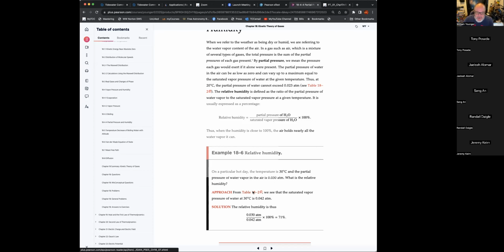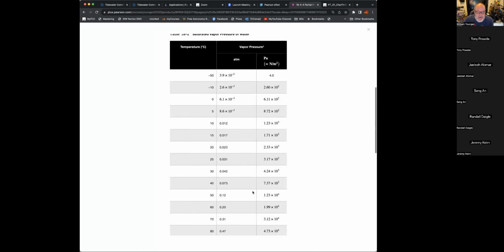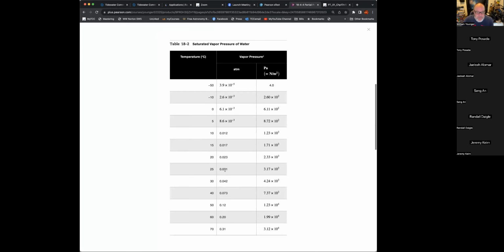So I click on table 18.2, and we said, actually, did I say it was 30 degrees Celsius? Yeah, it's 30 degrees Celsius. So you see at 30 degrees Celsius, the saturation vapor pressure could be 0.042 atmospheres, or 4.24 times 10 to the third pascals. The main thing is that the one they gave us was in atmospheres, so you want to use that.